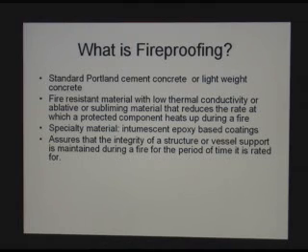Recently, we also used lightweight concrete, which is a mix of concrete with some vermiculite in it. There are other materials with low thermal conductivity. Some are ablative, some are subliming. These materials all reduce the rate at which the steel can heat up during a fire.